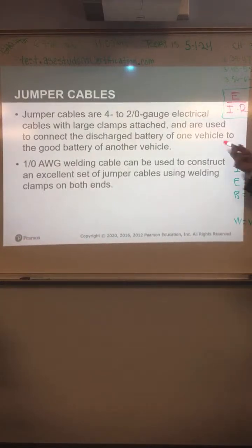Jumper cables. Everybody's familiar with jumper cables. If you ever buy jumper cables, don't buy the bargain brand. Don't buy the cheap ones. Don't buy the ones with really small cable. Chances are they're not going to start the car. Buy the good ones, the heavy gauge jumper cables. It seems like there's tons of cheap ones out there that just don't work very well. They just won't carry the current.